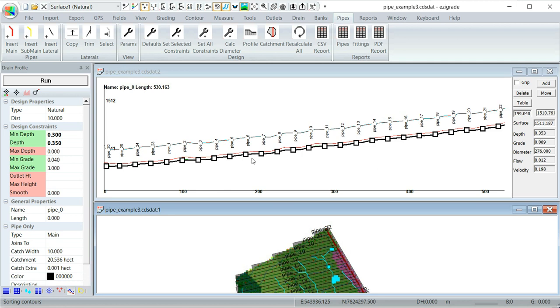But as we run down, we're getting up to a max of about 357 millimeters. That's calculated with the intensity of 9 millimeters per 24 hours. If you changed that to like 25 millimeters or an inch per 24 hours, this value will increase, and so will the flow and the velocity.